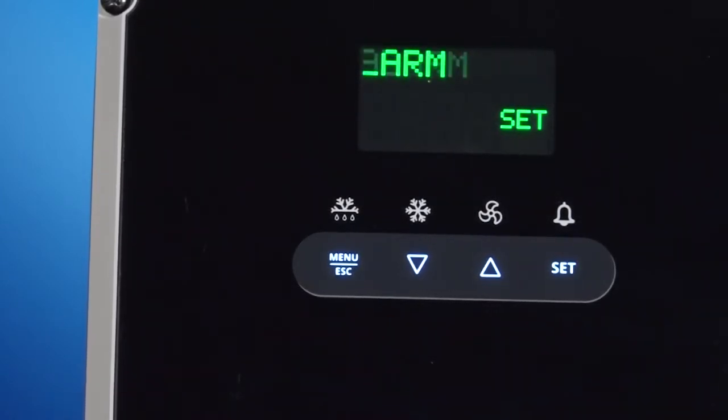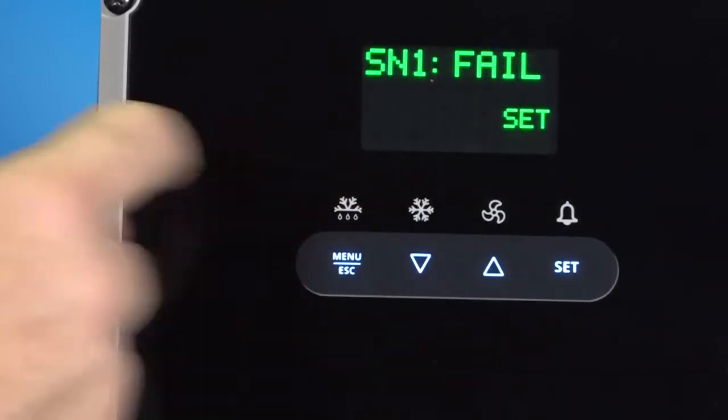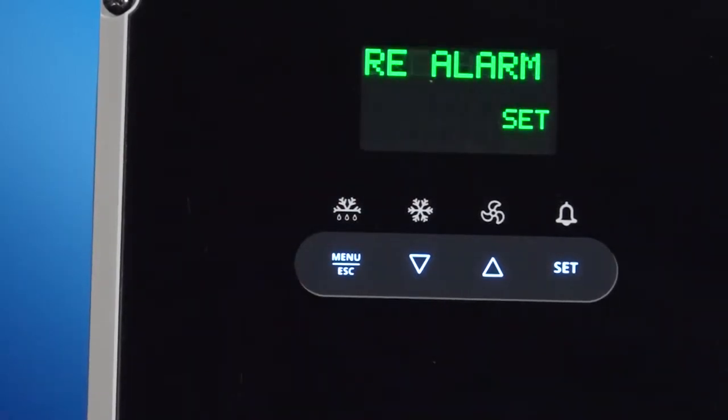After the low temperature alarm, the Sensor 1 failure alarm is selected. In this menu, all choices are the same, except the threshold value. If there is a sensor failure, the temperature setting is irrelevant, as the sensor cannot measure the temperature. The next alarm is the Sensor 2 failure. It is set in the exact same way as Sensor 1 failure.